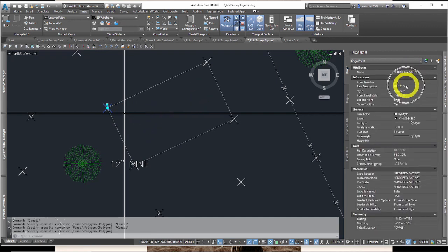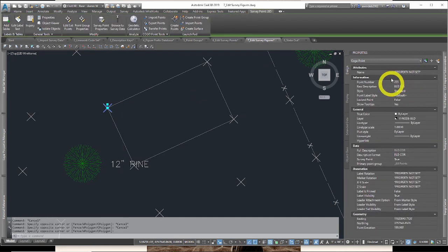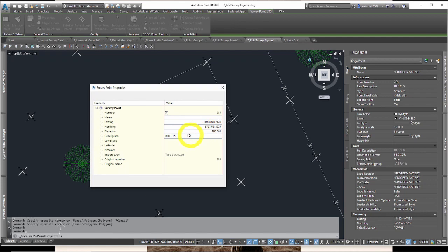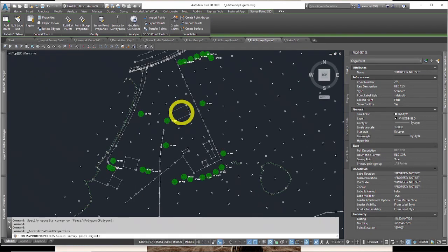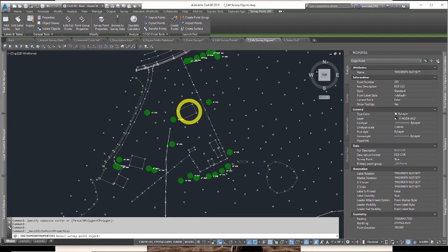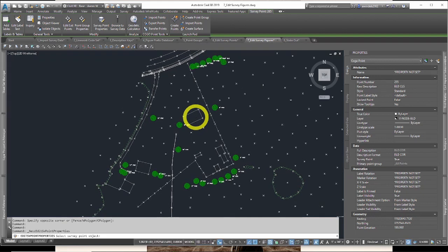So I just changed the coding of the COGO point by using the survey point properties to fill in the gaps and be coded the way that it wanted, so it would draft in a closed survey figure, which I have here. That's essentially the end of 3.7, just showing you one quick edit through, in my opinion, a little bit clunky survey database.